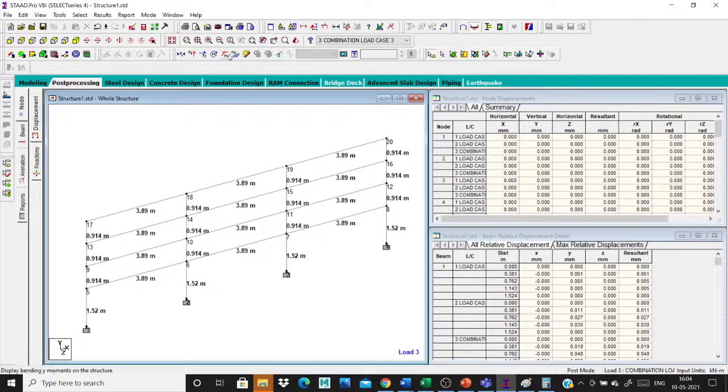These are the options. The first one is the deflection value; you calculate the deflection for your beams. This one is the beam stress. This is the main one, bending moment, y direction, z direction. This is shear force, y direction, axial force, and so on. This is the torsion force. Okay. Today we'll look at how to see the values; tomorrow we'll briefly discuss the bending moment values.